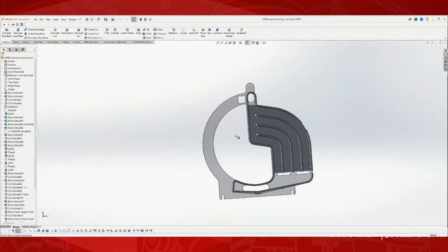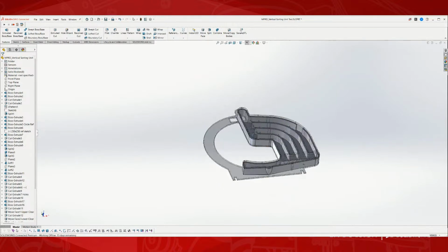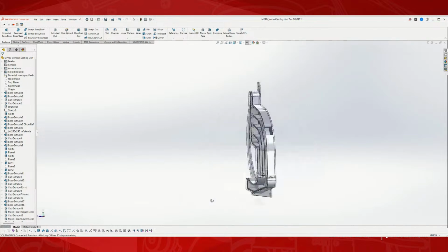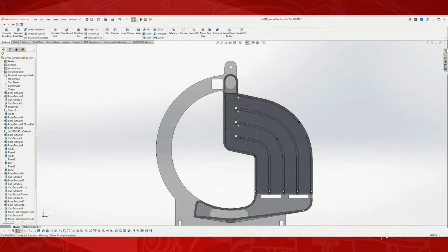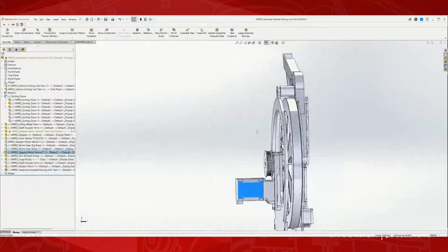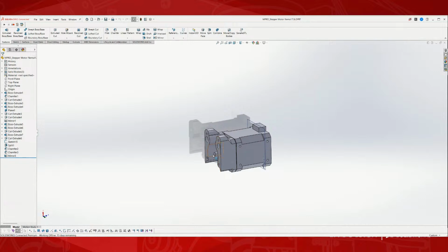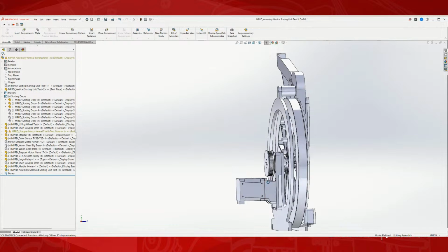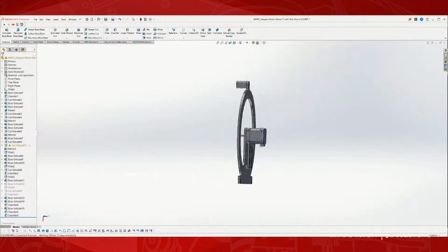So this right here, none of these parts are moving relative to each other. And you can see there's the front plate and the back plate and the way it all goes together. Since this is a static piece, I make this as a multi-body part. This is 8 pieces. And then when I bring it into this CAD, sometimes, like for a motor, for example, I'll often build the motor mount off of the motor. So you can see here, just like this. And I don't know where the rest of the parts are here. Oh, this was actually 2 different parts where I iterated, but this was the original motor mount system here.